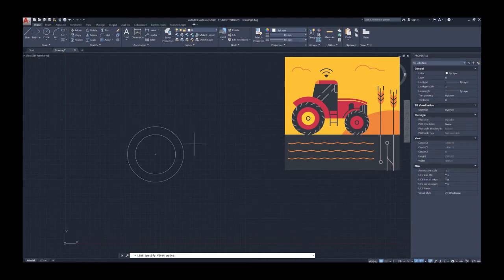Okay, so now we're going to draw a few lines that are going to help me form the guard of the tractor wheel. And we're going to use the trim function of AutoCAD. What I'm going to do is draw a line from the center to the very edge of the outside circle. And I'm also going to draw another line. In between the functions, you'll notice that you'll still be in the function even though you've pressed the place where you want to end.